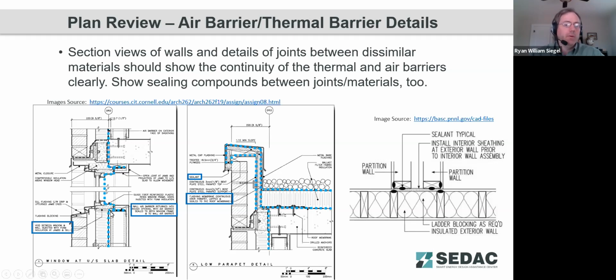And so anywhere we do have two things coming together, did we call for an appropriate sealant method and making sure to reinstate that air barrier. And throughout this, not only do we have wall assemblies, as you get up to parapet walls, how are you going to get that air barrier continuous all the way through there.